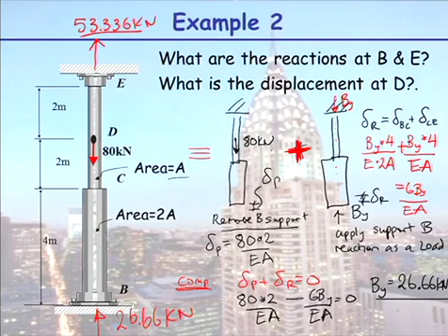And if you do look here, in this determinate system, this first one where we remove B, if I apply 80, this reaction here is equal to 80. And then when I apply a BY, the reaction up here is BY. So this 53.33 is actually equal to 80 minus BY. And this reaction down at the other end here is just equal to BY.